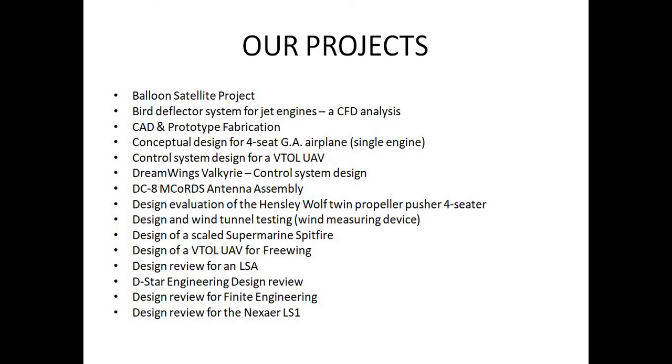The main project we have done in recent days is the swirl stabilized combustor. In jet engines, to reduce the fuel consumption and make it a very efficient engine, we are including a swirl combustor. By modeling that combustor through ANSYS we have done the thermal analysis, and we have generated one swirl combustor which is very efficient.